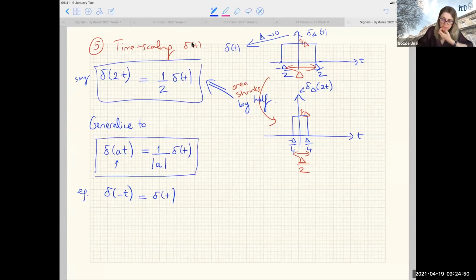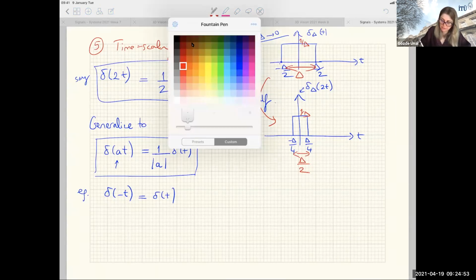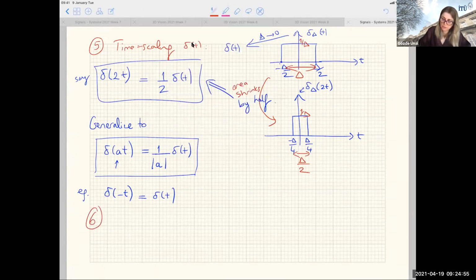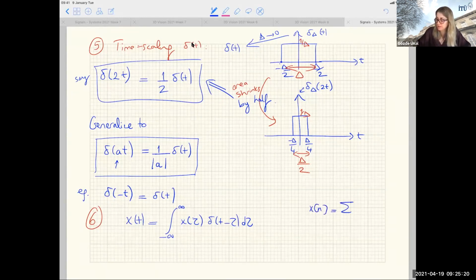And maybe I can say this as the last thing. I think we did this for discrete time signals. We can write any signal x of t as the integral from minus infinity to infinity of x of tau delta of t minus tau d tau. Here tau is a continuous variable. Before, remember, that was a k. So we wrote any signal as, remember, some k, right? X of k, delta m minus k. Deltas shifted to those k's, right?